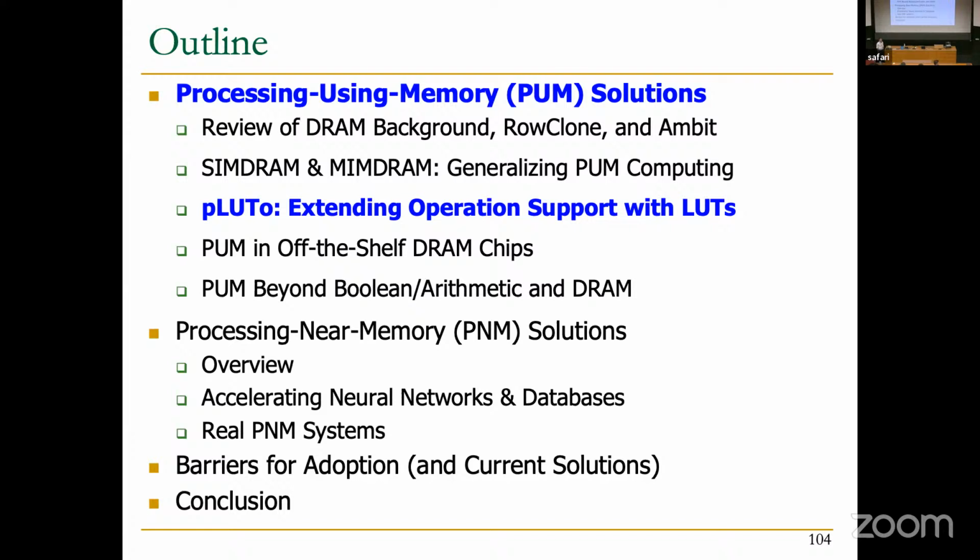Thank you for the talk, and especially thank you for working on this in-RAM computing, especially for the fact that you did not stop at the microarchitecture level and actually got to the programmer's level. Thank you. So can I assume that the compiler passes can determine which operation needs to run on the CPU, following up on one of the questions that was asked earlier? Like which instruction needs to run on the CPU and which one should just go directly to the RAM.